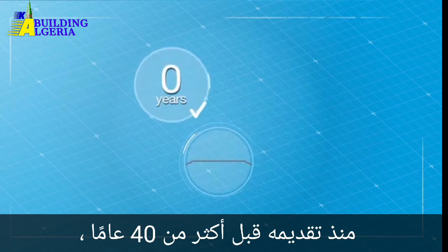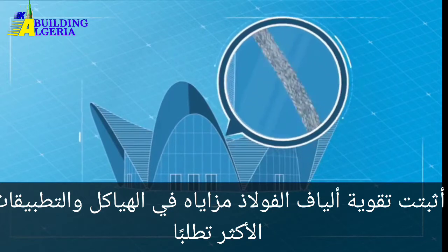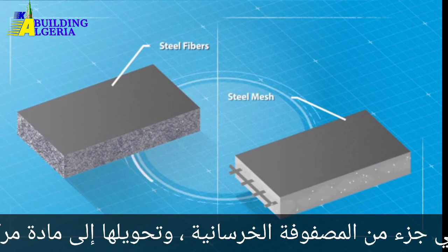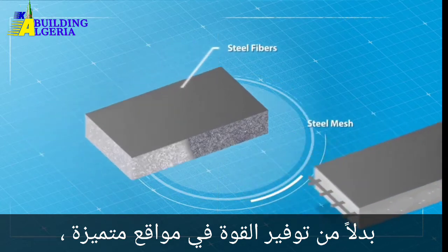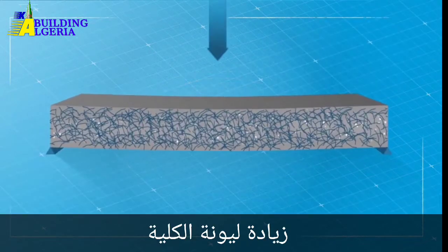Since its introduction over 40 years ago, steel fiber reinforcement has proven its merits in the most demanding structures and applications. The core difference between steel fiber and other reinforcement solutions is that fibers are part of the concrete matrix, turning it into a composite material. Instead of providing strength in distinct locations, steel fibers form a reinforcing network throughout the entire concrete structure, increasing its overall ductility.